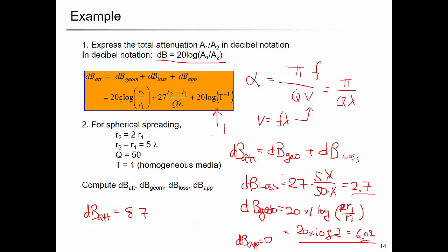But in the laboratory test, because you can define the geometry of the sample, you can eliminate this geometric spreading, so then you get only the material damping. So then you have a low-noise measurement.